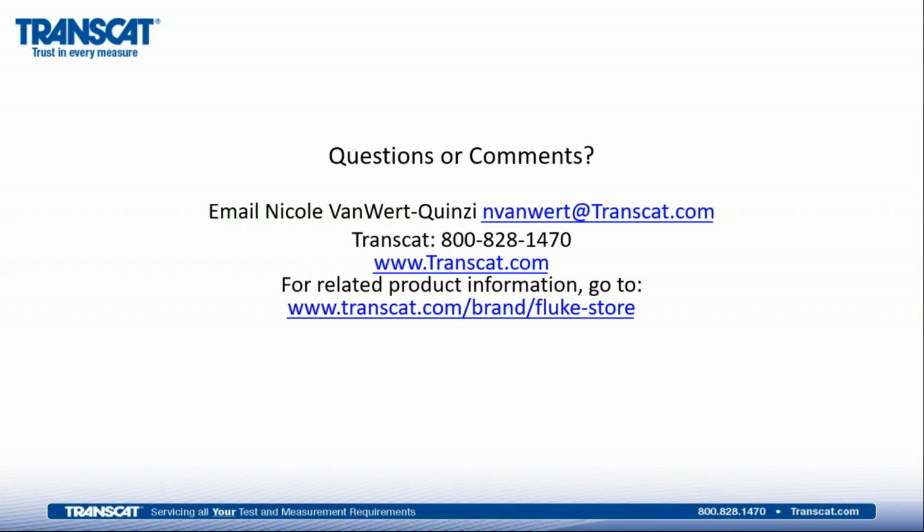The simple difference is when you're doing a milliamp signal source, the 24 volts that drives the milliamp signal is inside the calibrator itself. You would not want the 24 volt loop power supply from the loop in the circuit when you're using milliamp signal source, because you'd have conflicting power sources. Milliamp simulate expects the 24 volt loop power to be external from the loop calibrator.